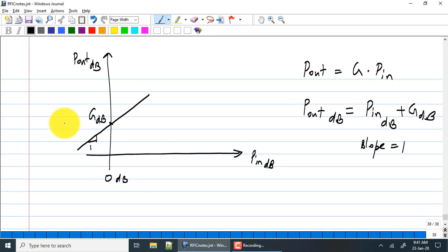As I keep increasing it, what I know is that eventually this will flatten out. In fact, many systems, because of other nonlinearity we will encounter in a couple of classes, it may even decrease after that. We will see why in the next class or the next couple of classes. So this output power is called the Psat, or the saturated power. This is true for any generic RF system. In fact, true for any generic analog system actually. You will hit a saturation.